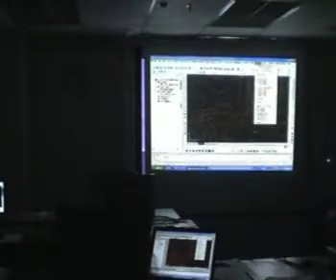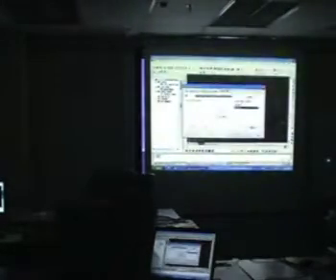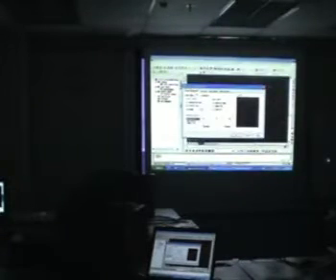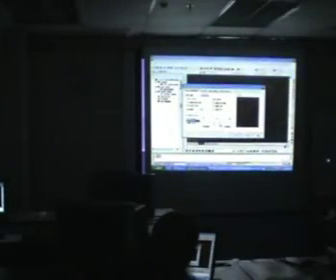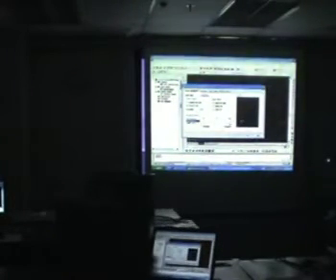Now, Land Desktop does have a Contour Style Manager in which you can change the contour appearance. Okay, we can look at the preview here. Smoothing options: at the moment, no smoothing means it's completely sharp. Add vertex. When you add vertex, maybe it's not so clear, but you can see that the edges are a little bit more rounded. Or you can use spline curve. Spline curve just means it's round.